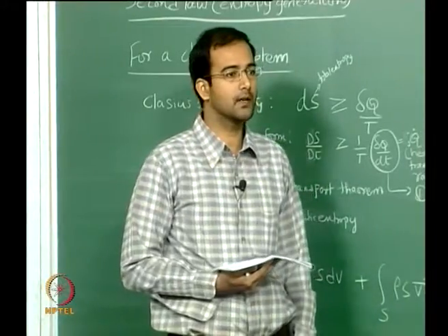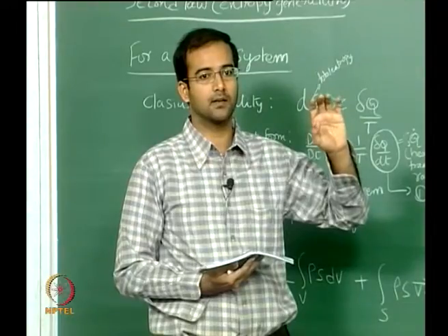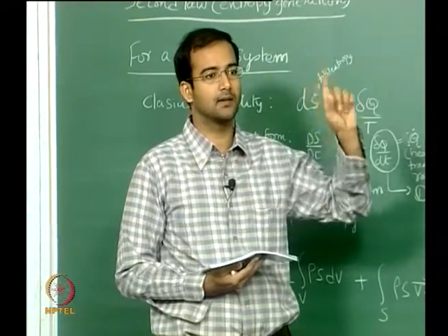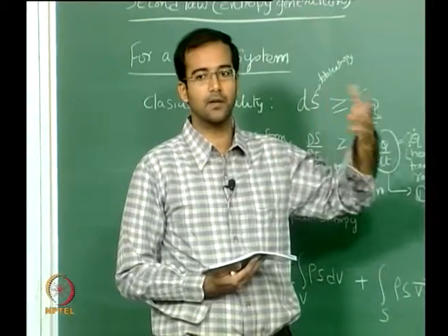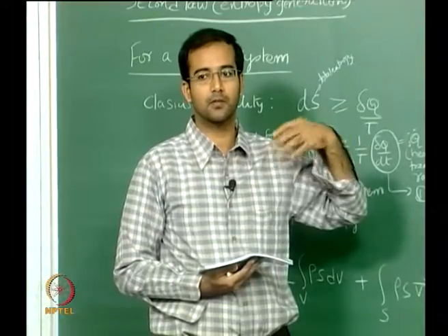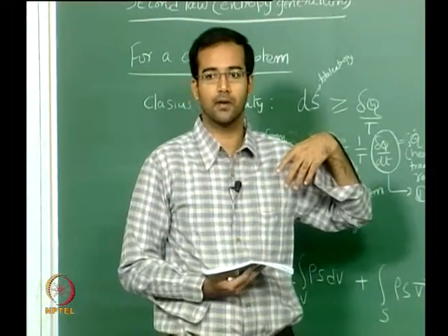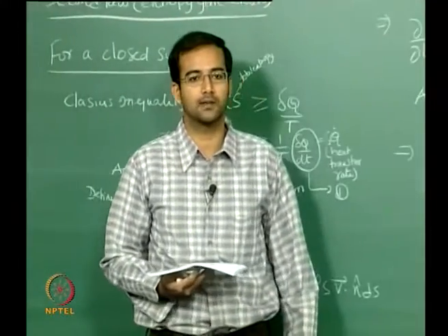If you solve the Navier-Stokes, we need equations for u, v and p, and if you are solving energy, again temperature. Now we don't have a separate equation for pressure. We have equations for u and v and the continuity equation, which is like a default equation.